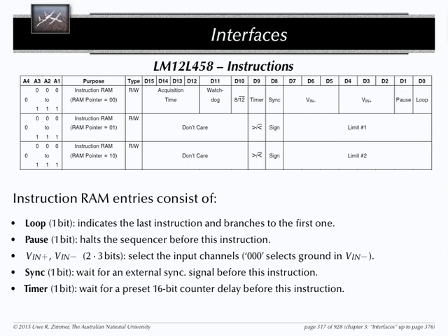Yeah, but it has nothing to do with noise, really. But you can use it for that. It's a clever idea. But in the first instance, it's a much more primitive thing. You just have a differential input instead of an input which is with reference to ground. That means you can measure stuff which is not necessarily relative to ground, but it can be relative to each other.